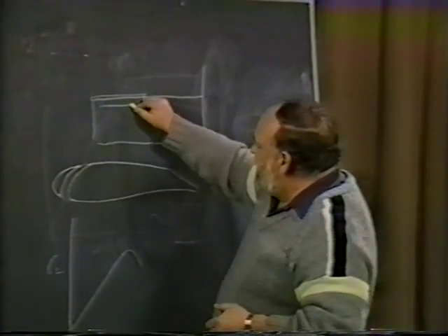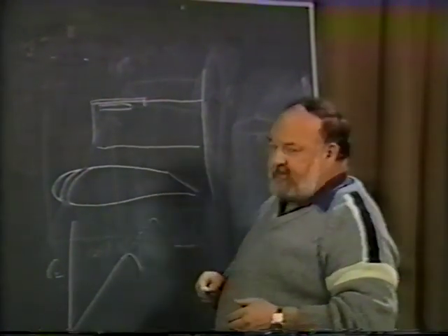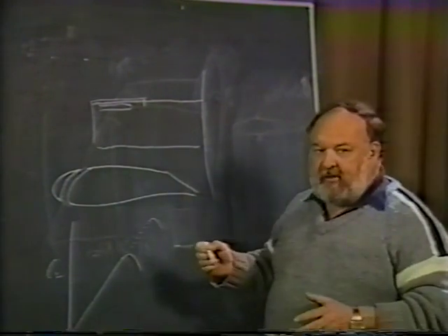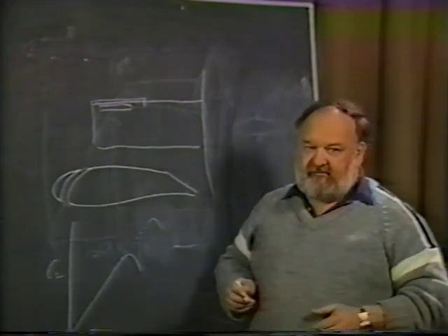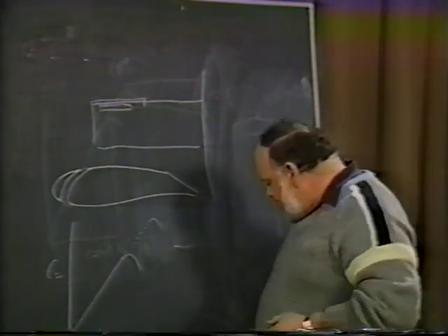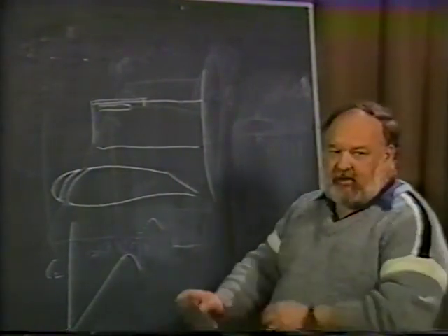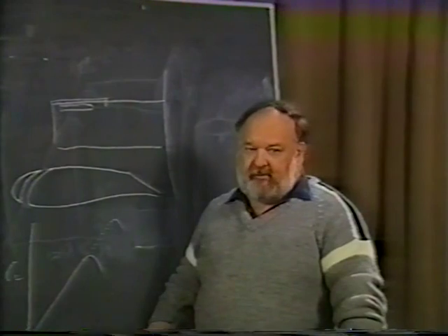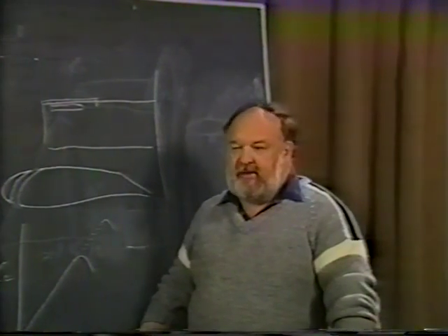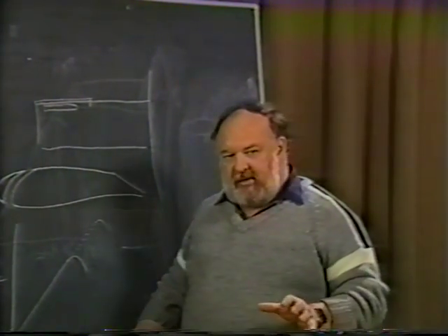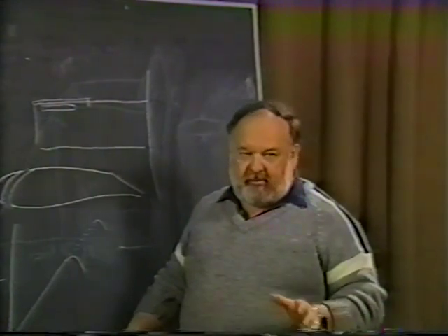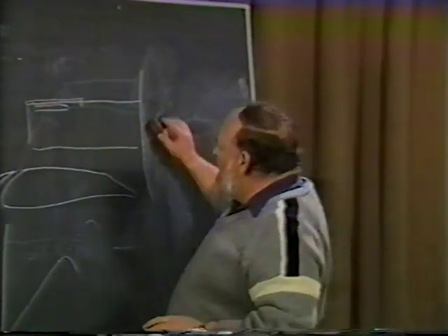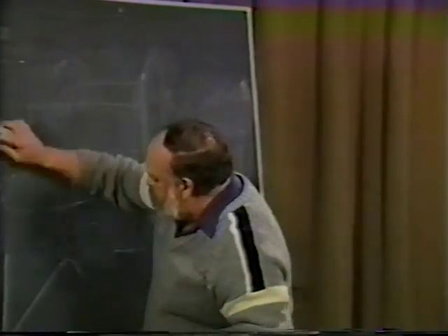But a fixed slot or a movable slot out here in the outboard section will give you that stall pattern and those spin characteristics that you're looking for. It will do a good job. There are some other subtle things you have to watch out for. When Dr. Raspet down at Mississippi State was doing a lot of work on a Cessna L-19, they started using boundary layer control, suction boundary layer control, blowing boundary layer control. And one of the things they found that occurred was sort of strange.